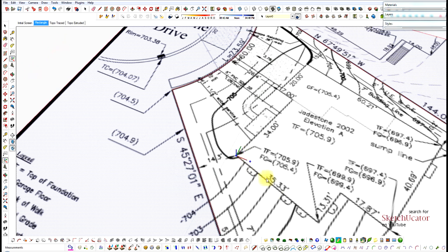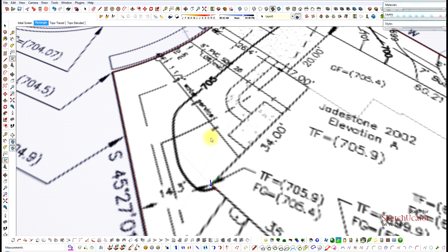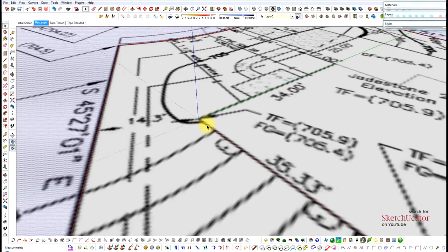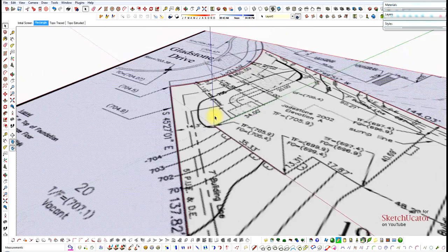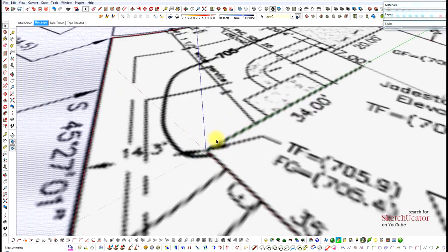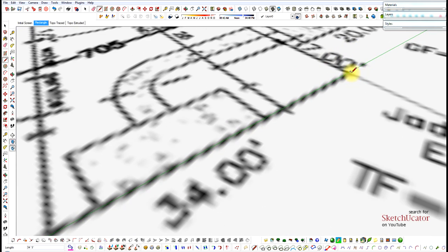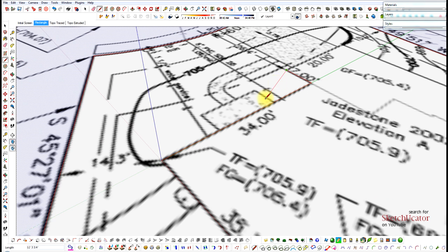So to get this as much as you can correctly, go out as far as you can with that red. The green, if you notice, is already pretty well aligned. We'll just carry that out. So you see the axis now has been reoriented to the house. Very simple now to trace the whole house and accomplish 90-degree corners because the axis is in the right spot.